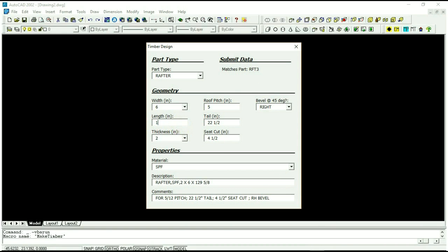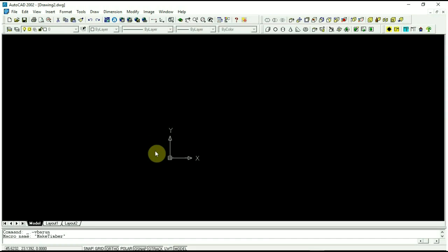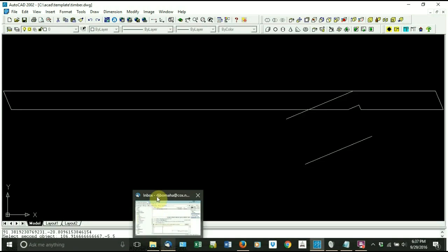So I say, okay, I'll make the next one, see if they're in there. The next jack rafter will be 103.625, and I'm going to give it a left hand. Since it doesn't have that in its database anywhere, it'll allow me to add it. I hit right, and it allows me to add that. It's Rafter 4 and 5 now. And if I go back and hit left, it knows that Rafter 4 has already been defined. So I'll just hit Submit Data, and it'll make both of those rafters and add to the database file.